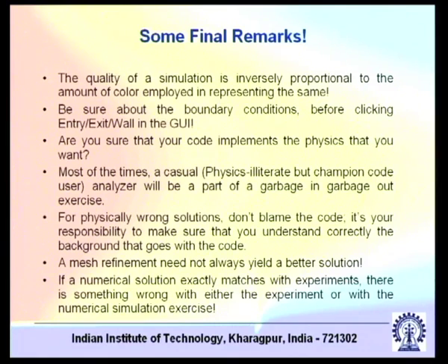Then there are certain issues about meshing. Theoretically we always learn that a mesh refinement will always give a better solution, but practically a mesh refinement to an unlimited extent may not always yield a better solution. The reason is that when you go for mesh refinement, you are sometimes dealing with small numbers, because the grid sizes are small, and those small numbers can interfere with some of the calculations, and with round-off errors and so on. So a mesh refinement need not always yield a better solution. In theory yes, in practice maybe, maybe not.